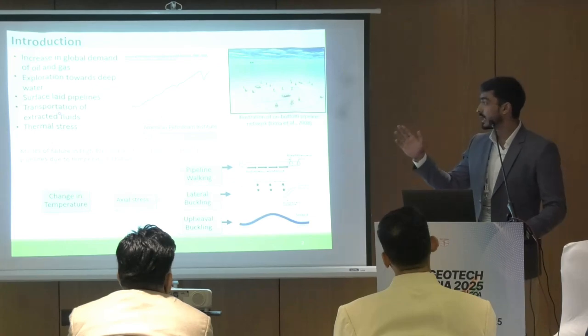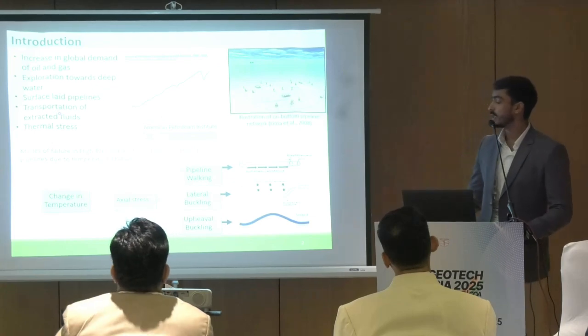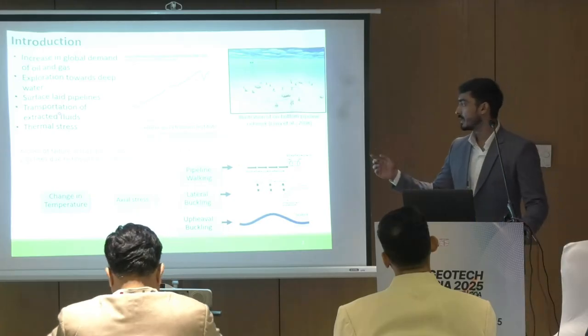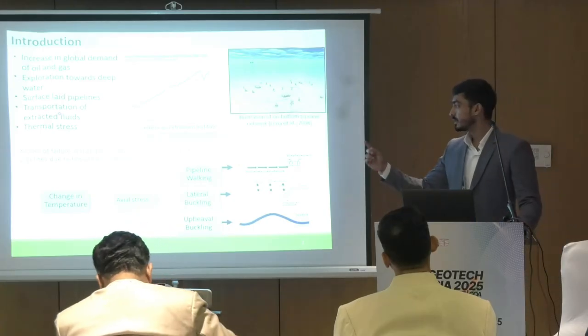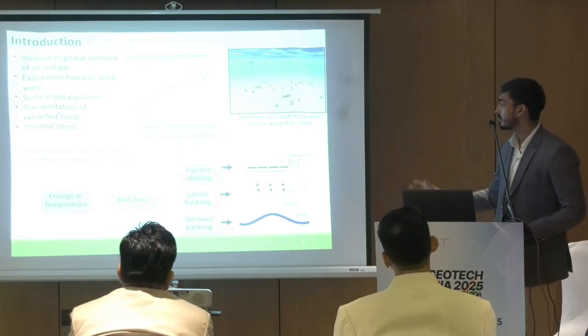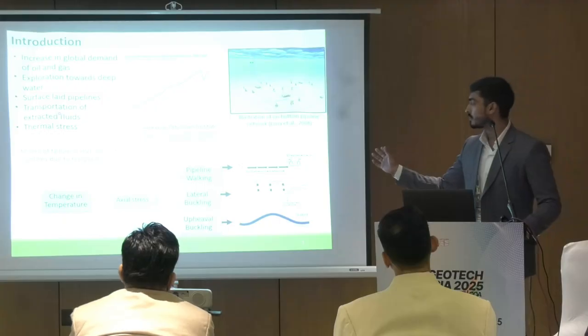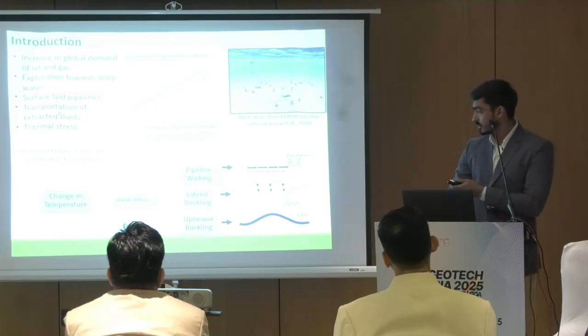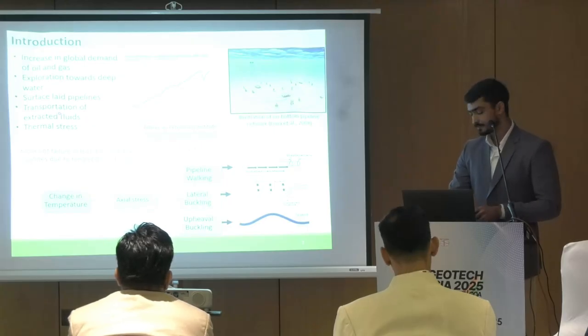So due to this axial stress, change in temperature, axial stress will come into the pipeline, and the pipeline will fail in 3 modes, which will be pipeline walking, which is very critical at the end, and maybe at subsequent part of the pipeline lateral buckling may happen, or critical and upheaval buckling may happen.